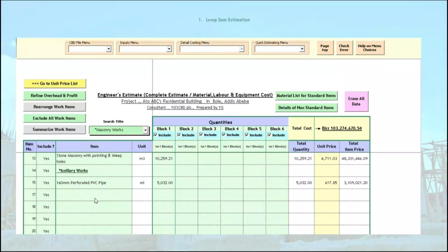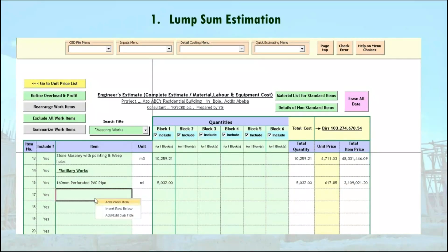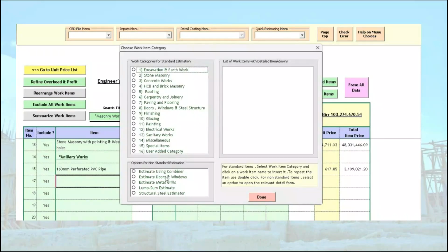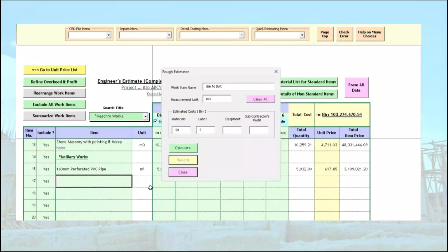1. The lump sum estimate. This method is useful when the cost components of the item are fairly straightforward or the nature of the item calls for outsourcing and a specialized subcontractor quotes for the complete rate for the supply and installation, thus there is no point in making detailed calculations. In such cases, we use the lump sum estimator to easily add up material price, the labor cost, overhead, and profit margin, and we are all done. The unit price for supply and installation of an elevator, a light fixture, or a J-bolt may be good examples.